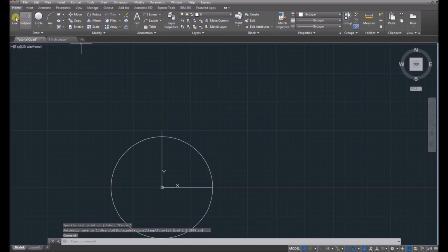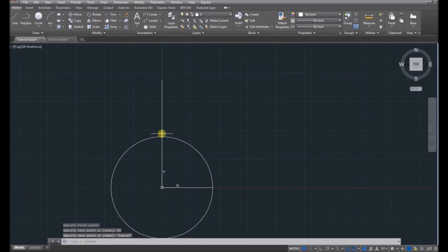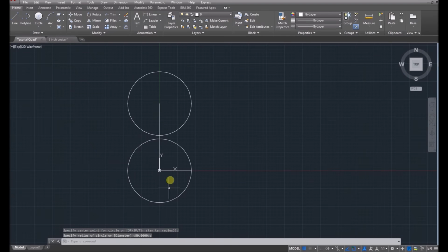And then I'll actually draw up 89 again. That 10 millimeter distance there, if I was making a frame for 3-inch props, for example, I would only make that like 5 millimeters. But realistically, the bearings aren't going to give out that much slop that they're going to hit, so you could probably even go 2 millimeters. I don't know, but better to be safe than sorry. Okay, so then I've drawn the second prop.